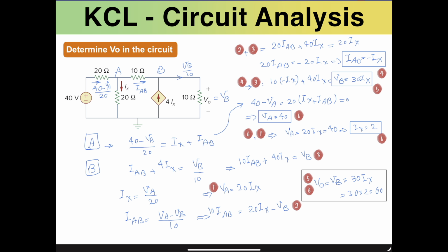You can see that this needs a little bit of work in terms of identifying first the currents passing through each element, and then applying nodal analysis on the nodes that we have identified properly. However, when we do that, we may end up with fewer equations compared to unknown variables. Then we have to search a little bit more in the circuit to find other equations, such as these last two. They would help us find more relationships between unknown variables. Then it will be simple math equations that we need to solve.